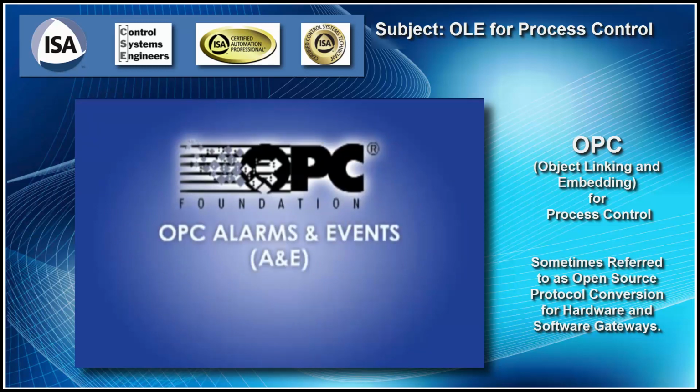OPC Alarms and Events, A&E, which provides real-time OPC alarm data where rules can be configured for determining when a point goes into an alarm state and the level of information to be made available when an alarm is raised.